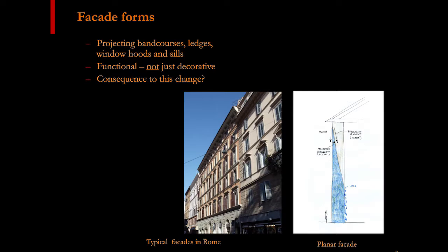But from a water management standpoint, you can think of it as if we were to cut a section here, tint the water blue, and start spraying water on this wall. What you'd see is there are 2 forces acting on the water. Gravity is bringing the water down, and absorption and capillary action is simultaneously bringing it in. So the gradient, if you could see where the wall is wet and slice a section right through it, is actually migrating inward and forming this triangle.